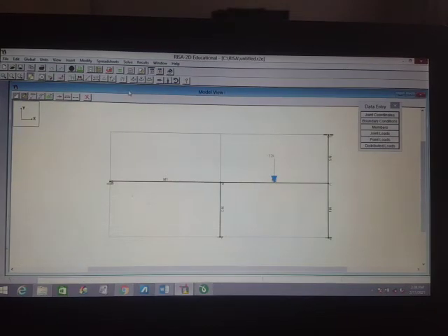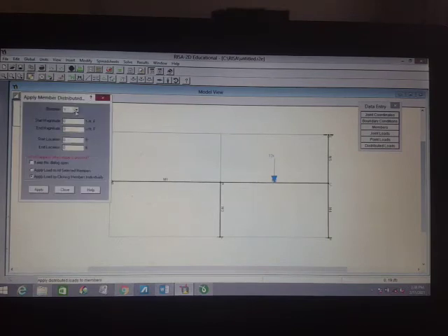The next thing that we'll do is the distributed loads. So for distributed loads, we'll just click here. Then what's the direction? By the way, for distributed loadings you can also have the equivalent. Let's say you have a wind load along the roof of a portal frame. Then it can also translate the values in terms of the vertical or the lateral. So you can explore this for our problems in portal frames.